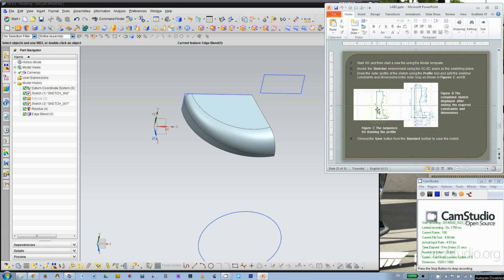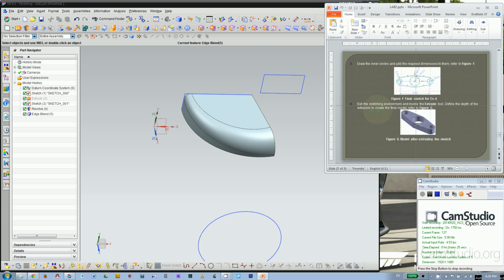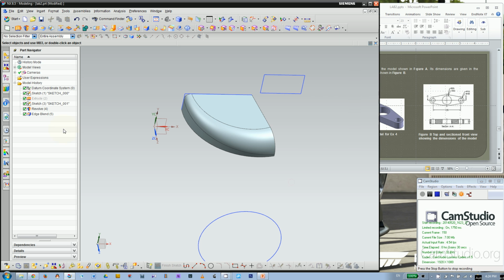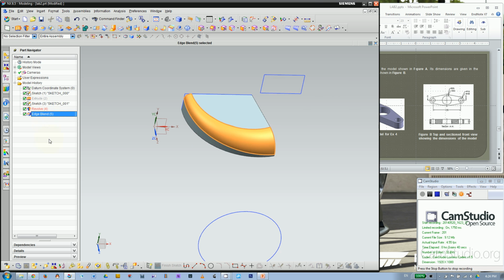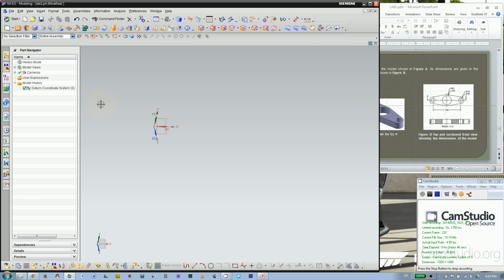So let's say, maybe let's start from this one with 3 holes. Okay, and I'm going to clean up those. So in NX, you can use basic Windows keys. Like you can hold down Shift and click the bottom one, click the top one, that will multi-select all the features. Right click, and delete them. Right now I have a clean file.